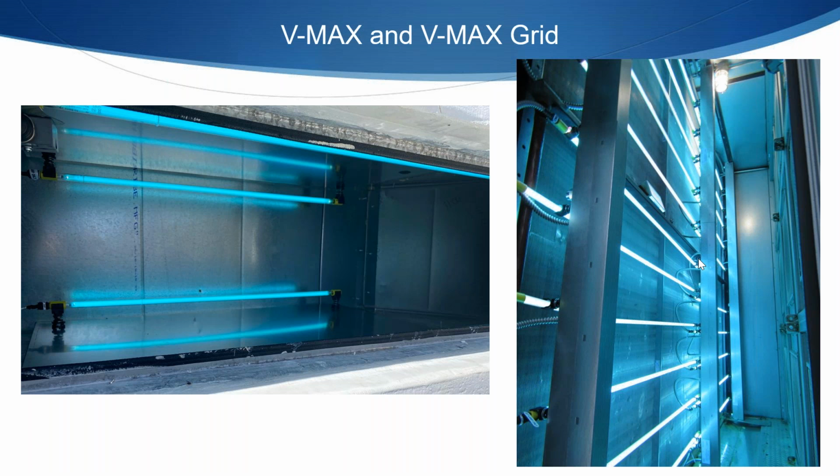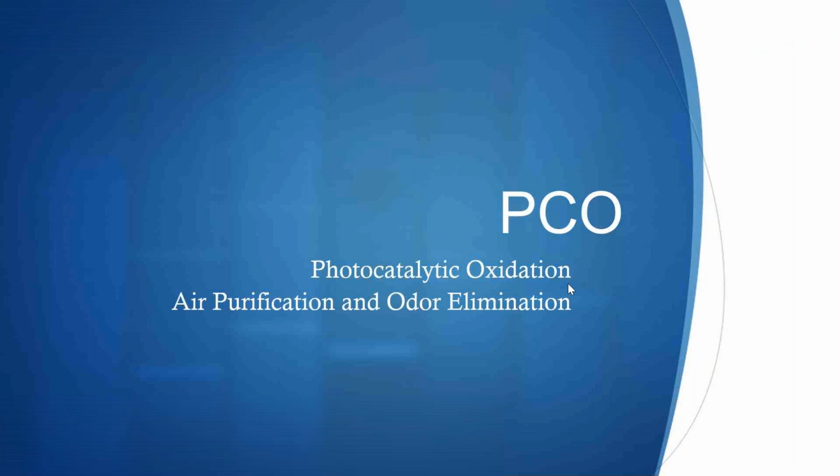There are safe levels of established UVC impact, and the current established level is 6,000 microwatt seconds per centimeter squared per 8-hour period. You will get greater than that dosage in less than a second in an application like this, and the next picture I received after this was of a pretty good sunburn. UV acts on the top layer. It doesn't penetrate deep through the surfaces. UVC does not. So I guess the positive news is that although he had a pretty good burn on his skin, there's not a high level of cellular damage, but that's not really good. That's not a good practice. So let's make sure we get our safety on there.